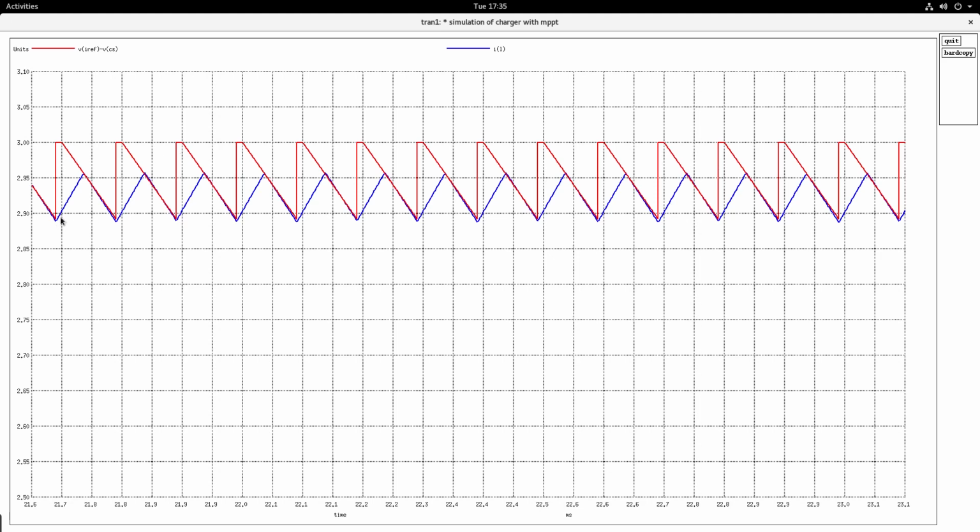And you see the moment the inductor current hits this at the down slope, the SR latch changes state, switches off that device, and then the inductor current is falling. So on, it keeps going. This is also behaving exactly like what we anticipated, and you see that the inductor current is controlled to whatever value that you set.